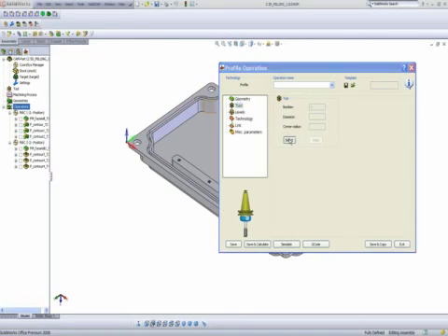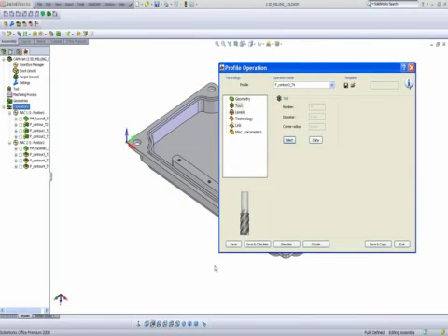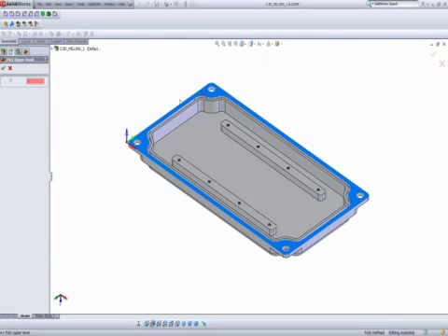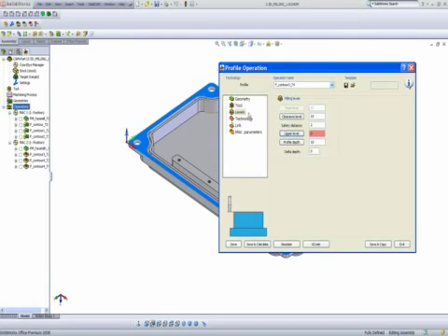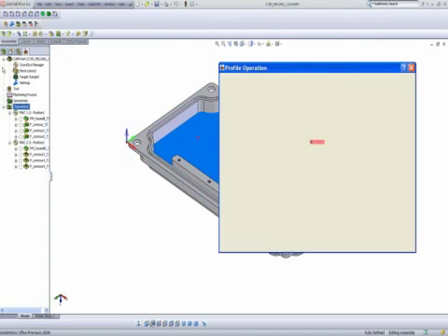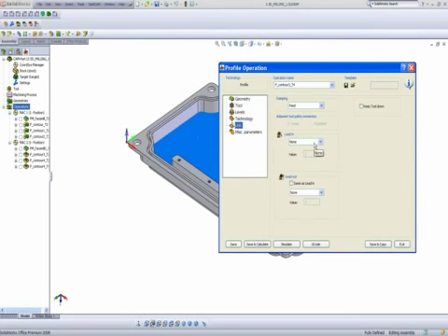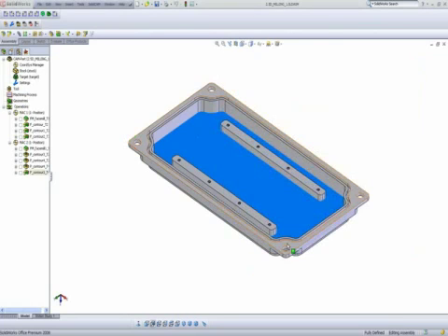The tool that I will be using will be tool number 4, my 6mm end mill. My levels will be my upper level from very top, and my profile depth will be at the very bottom. Now my technology, I'll be working on finish only, and in my link area I have my lead in of arc, and I'll have the same thing with my lead out. If I have to do save and calculate and simulate right now,